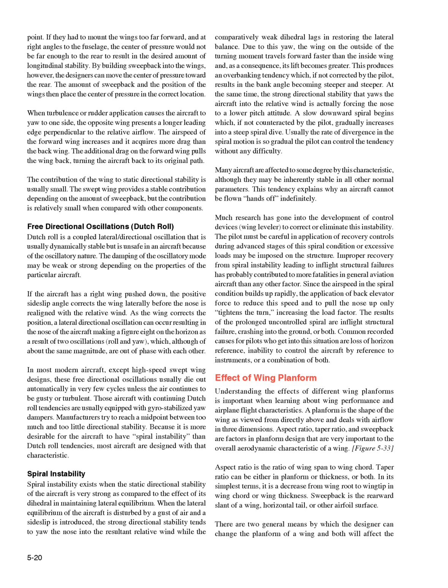The contribution of the wing to static directional stability is usually small. The swept wing provides a stable contribution depending on the amount of sweepback, but the contribution is relatively small when compared with other components. Free directional oscillations, Dutch roll. Dutch roll is a coupled lateral/directional oscillation that is usually dynamically stable but is unsafe in an aircraft because of the oscillatory nature. The damping of the oscillatory mode may be weak or strong depending on the properties of the particular aircraft.